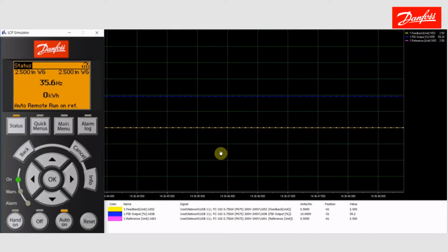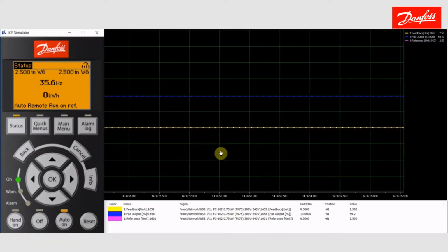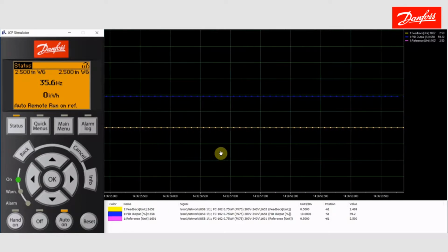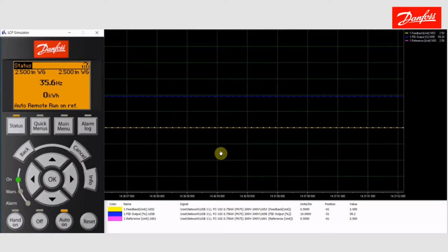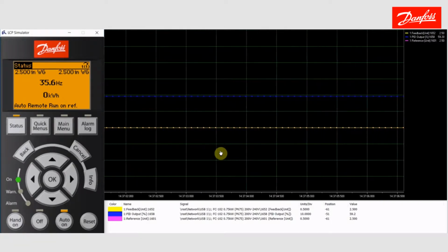To summarize, higher gains are more aggressive, generally speaking. Lower integral times are more aggressive. You want to find a nice value for the two. You may want to start out with defaults and see if the system responds accordingly. If not, I would first attempt to do the PID auto tuning. Once everything is in place, the transducer is connected, the system is ready to run, try the auto tuning.